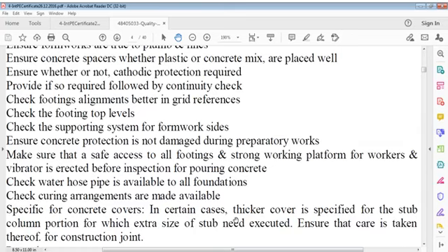First of all, we don't allow rusted bars. Whatever rust is there should be removed by whatever method, or there should be protection to steel bar storage every day or time under polythene cover. And bars are stored above ground level. You have to make some platform so water does not reach them immediately once they are in contact with the ground.